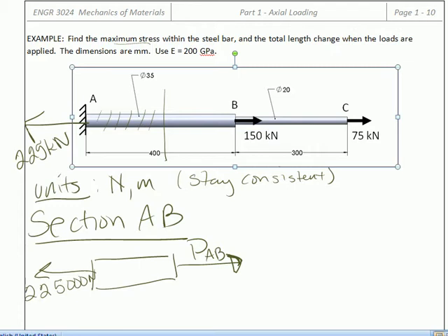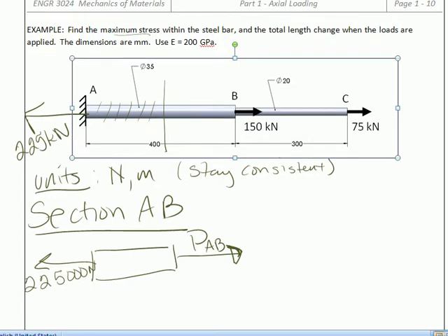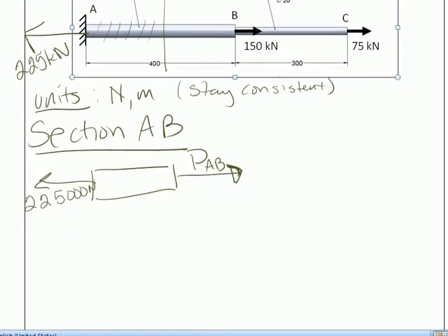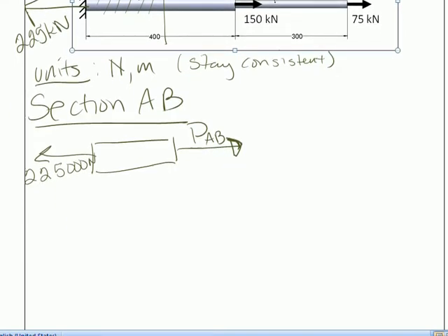With only one force going on, such a free body diagram seems trivial, but for thoroughness and to keep things clear as the problems get more complicated, it's always a good idea to go back to the basics and do the free body diagram. From here, we write the equilibrium equations.